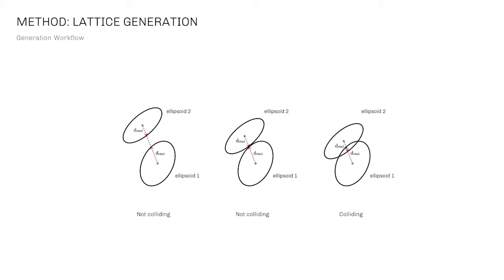The dense packing is realized by iteratively adding the new ellipsoids and relaxing the existing ellipsoids. In each iteration, collisions are checked between pairs of ellipsoids. This process is very complex and computationally expensive for ellipsoids because the ellipsoid collision point doesn't necessarily sit on the line that connects the centroid as it does in spherical colliding. To simplify this process, the orientation difference of the two colliding ellipsoids is assumed to be small. Hence, the collision point is still assumed to be in close proximity to the connection line.